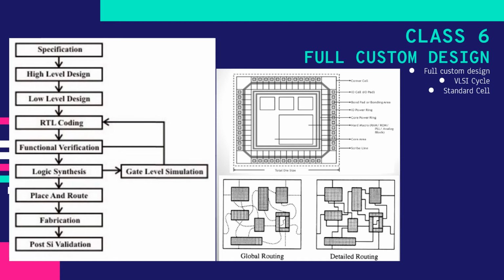We ended the class with a brief of standard cell. Standard cells, also known as semi-custom, have some predefined libraries, and all the commonly used logical cells are developed, characterized, and stored in the standard cell library. Typical libraries contain a few hundred cells, and each cell is defined with a fixed height that cannot be changed.